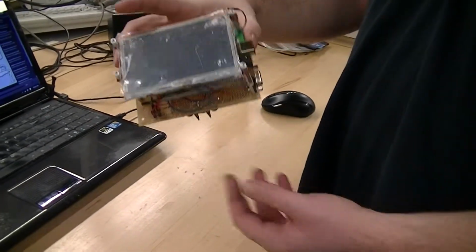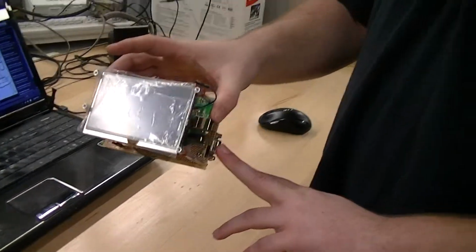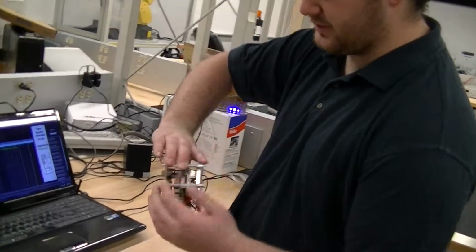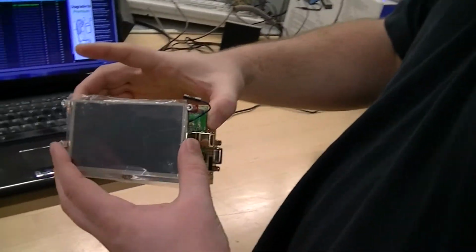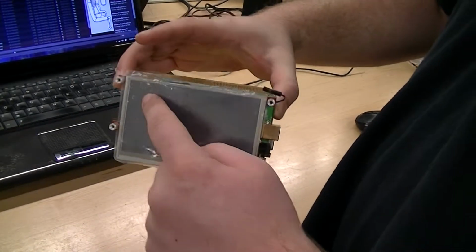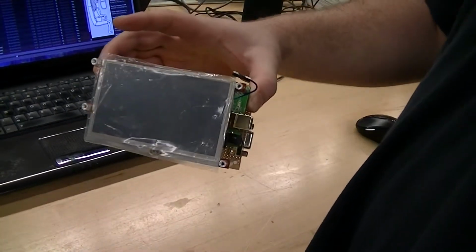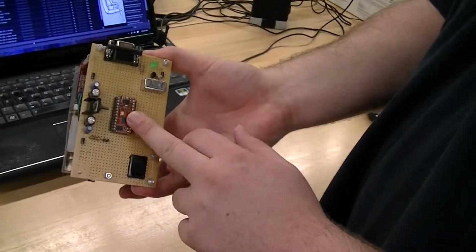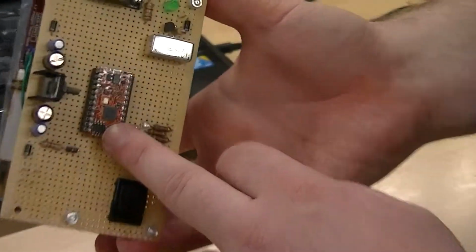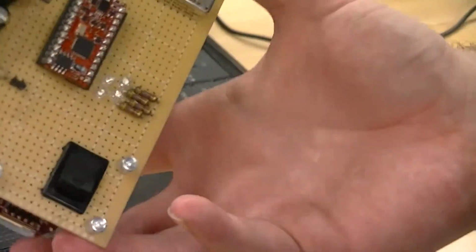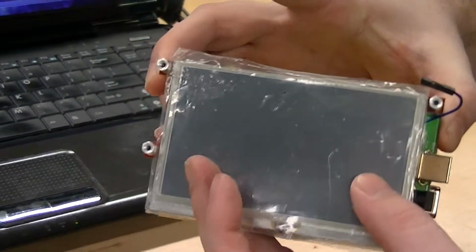So essentially I plug it in through the OBD2 sensor through this port, and it communicates with this chip, the HCS12, and this touchscreen. When it's done, I'm going to be able to hit a button on the screen, say for speed. It's going to talk to the HCS12, which is going to tell this chip what to send the car. The car's going to get the values, and then it's going to send it back as fast as it can, and it's all going to come back and display the speed on the screen.